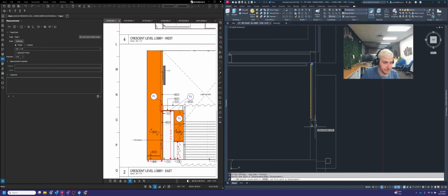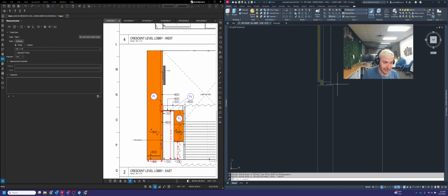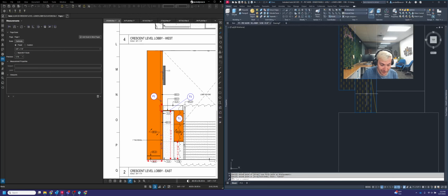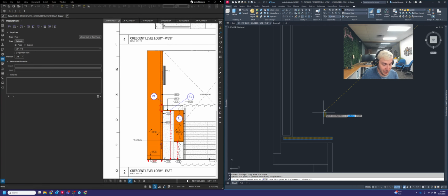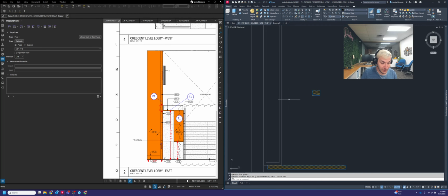Okay. Then you've got that same exact reveal block there. And we're going to come over to here, and we're going to add these in as well over here. So I need to rotate this one so it's facing the correct way. My MDF should be facing out towards the room.